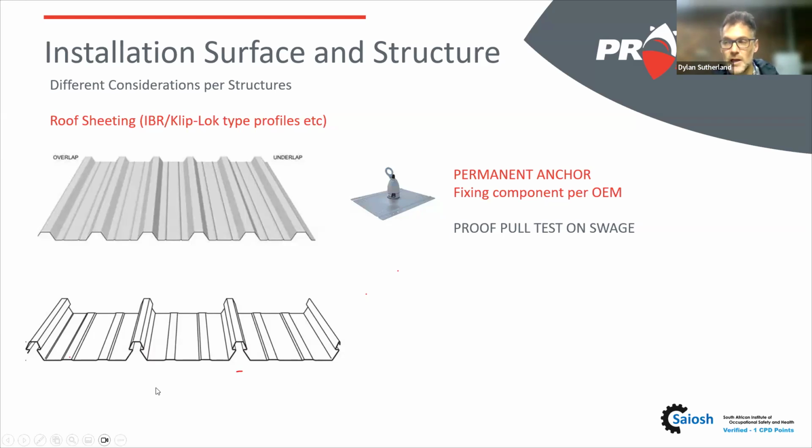So it is really critical that we think about these, because roofs are massive investments. You don't want to be breaking the roof because you've bypassed something from a safety point, or unknowingly connected something to a product that you believe will work. There's other elements to this. I mean, there's some solar fixing clamps that are being used on the clip lock sheeting.